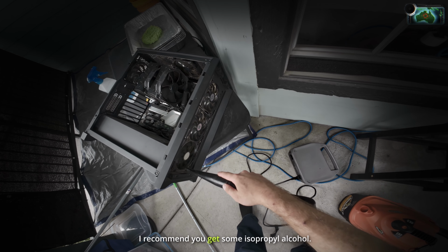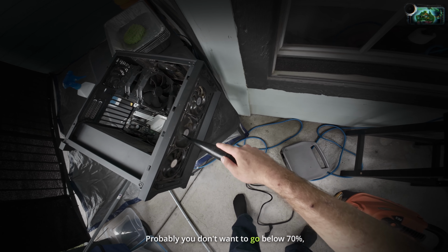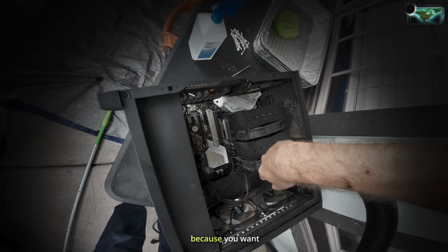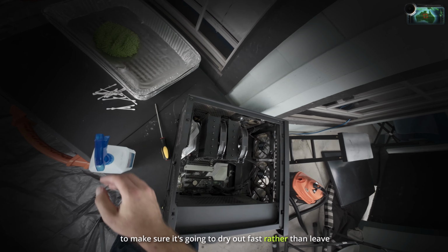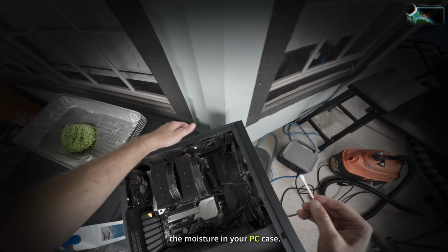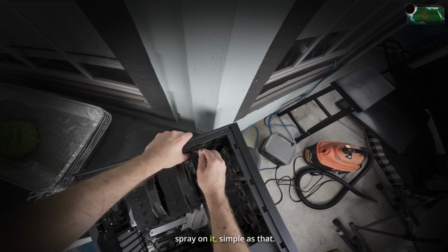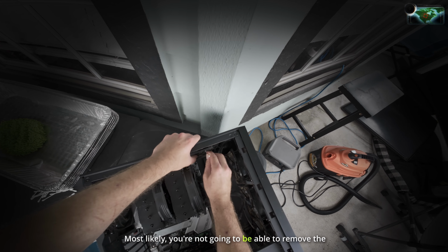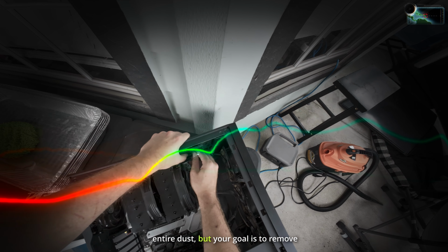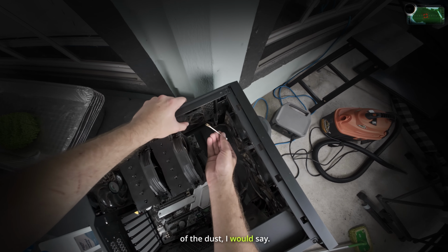I recommend you get some isopropyl alcohol. Probably you don't want to go below 70% because you want to make sure it's going to dry out fast, rather than leaving the moisture in your PC case. Get some cotton swabs, spray on it. Simple as that. Most likely you're not going to be able to remove the entire dust, but your goal is to remove at least 70% of the dust, I would say.